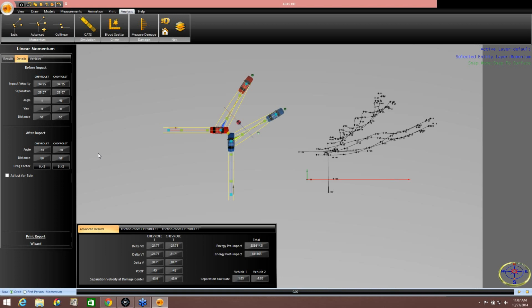I looked at the deceleration or the marks after impact, determined that all four wheels were free to rotate. There were times when the cars had a full 0.7 when they're sideways, and there were times they didn't when they were rolling straight. So we went right in the middle of that, 0.42. Now remember, the vehicles were doing 60 and 20. So let's see if I'm right.